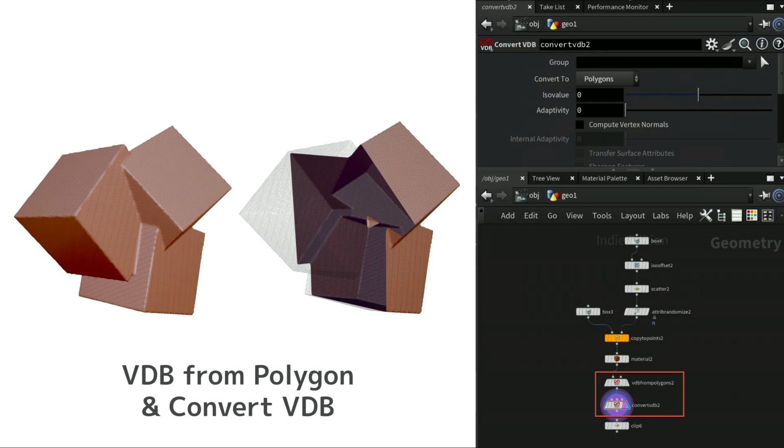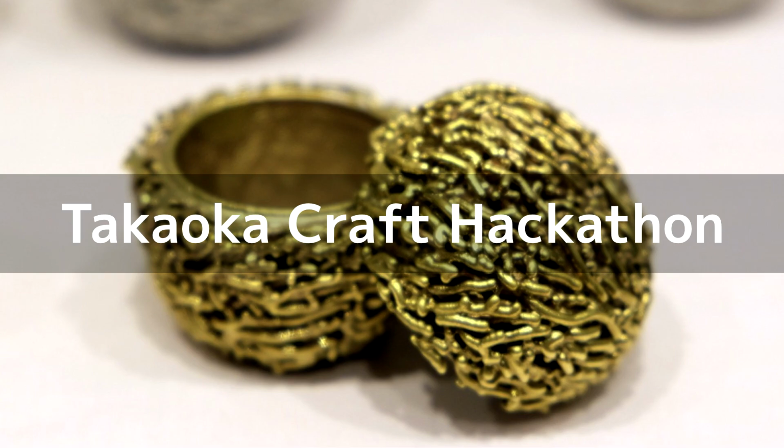However, there are downsides as well. You need to specify resolutions for the VDB operations, and if the resolution is too low, the edges of the hard geometry object may become slightly rounded. So despite this, the method is highly effective for ensuring 3D printability. So in most of the cases when I do 3D printing, I use VDB operations on most of the objects.